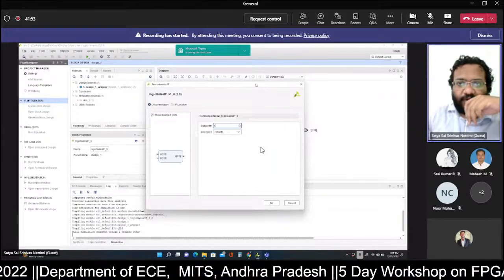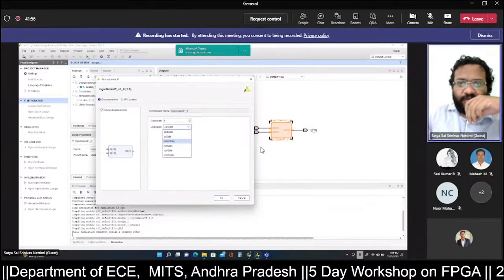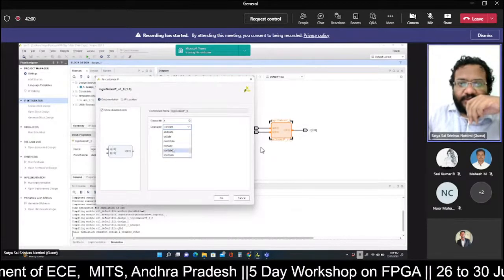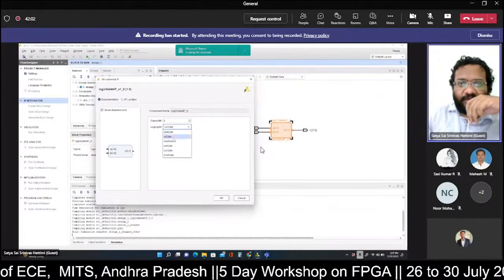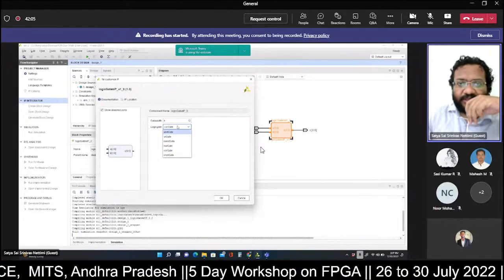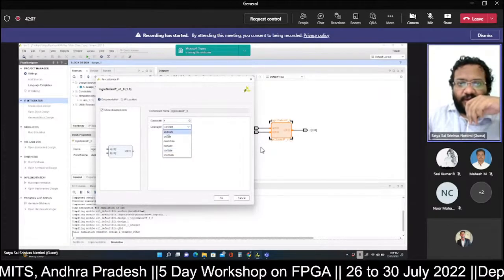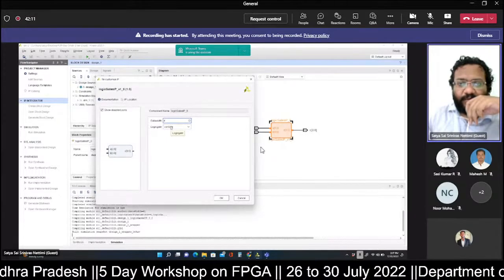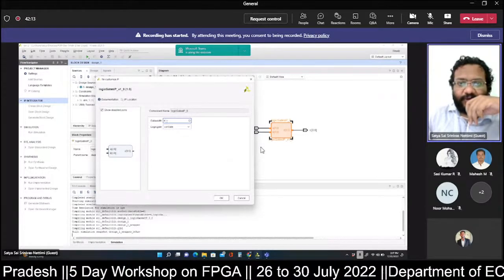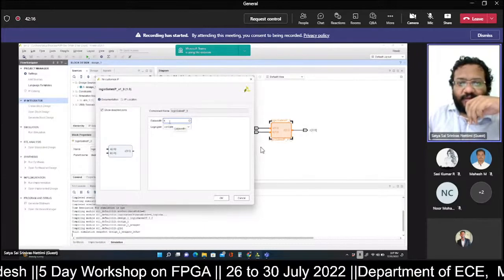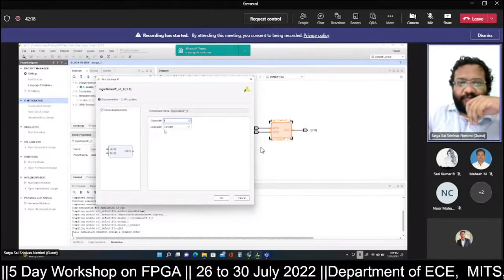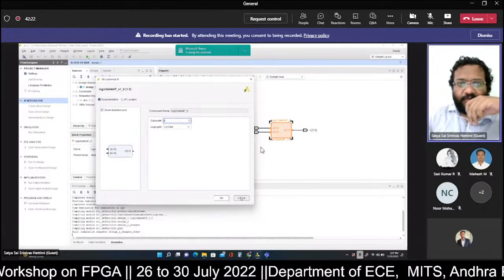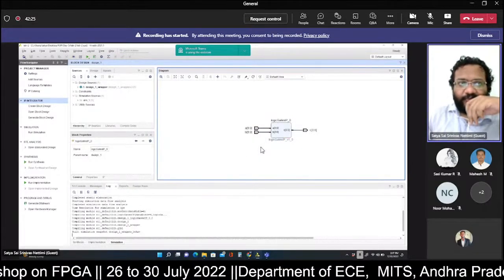In this example, we have clubbed all the architectures of logic gates and packaged them in the form of a single IP, and we provided a customization window. We made the ports of variable bit length, and as per the user defined parameter, the port widths are scaled up automatically with respect to the IP.